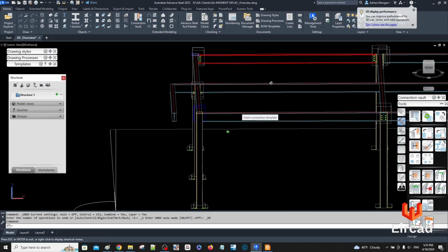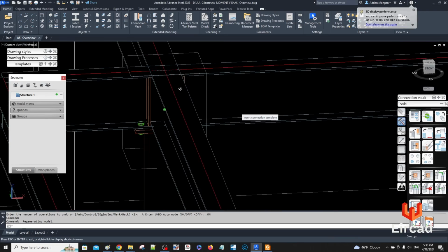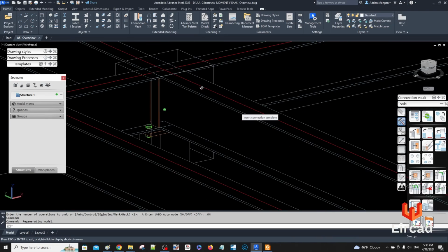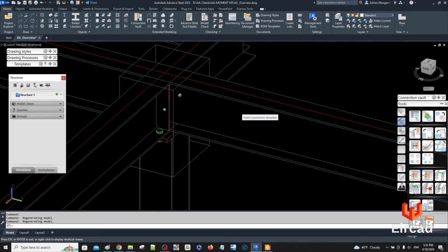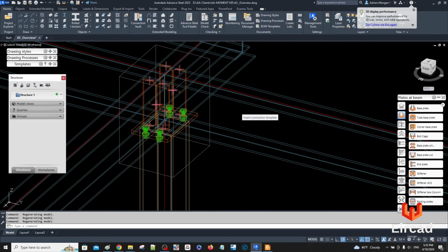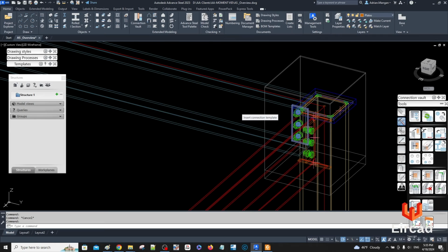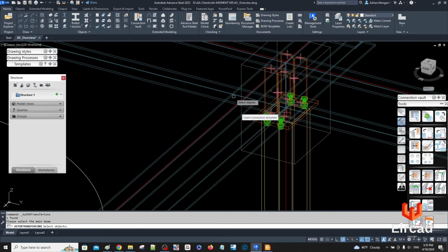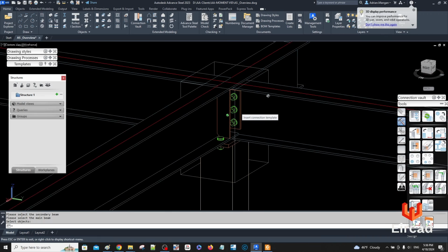Alright, so we need to put a connection in there. There's not going to be enough room unless we use smaller plates, so we'll probably use a shear connection. So let's go to our shear connection again. What I can do is you can just start from one of these and just grab this one here. Make sure you use this copy connection so they're not connected. But this time I'm going to do a beam to a beam. And you can see what we have there.